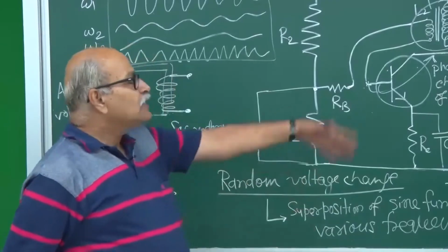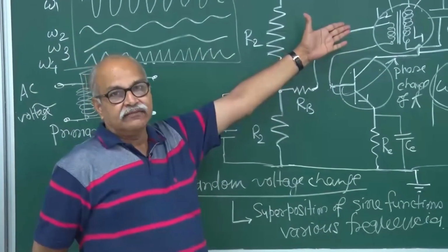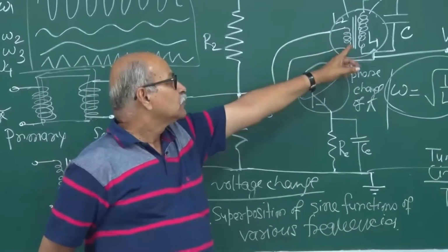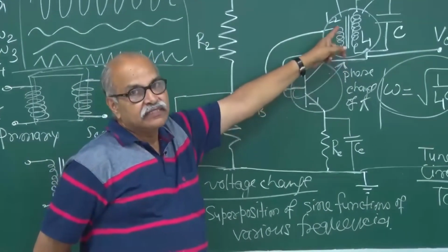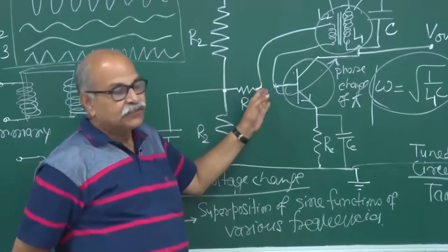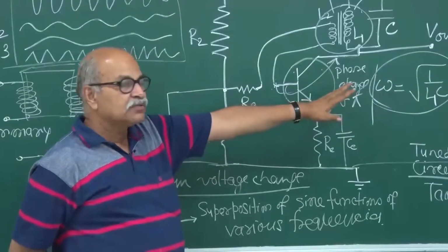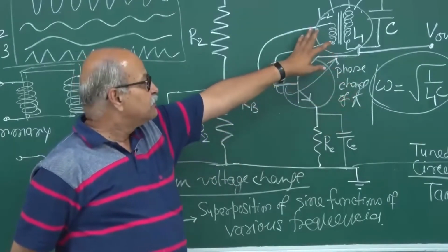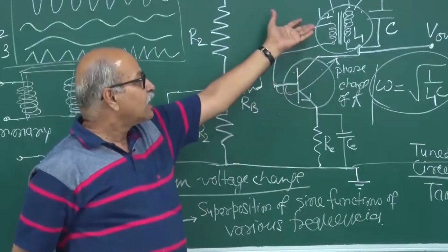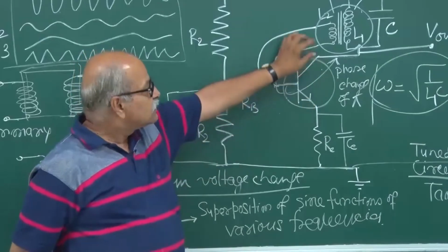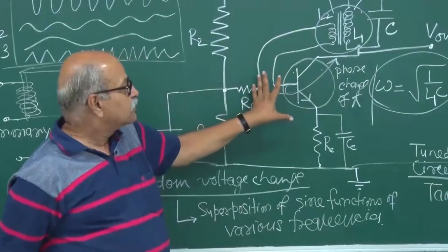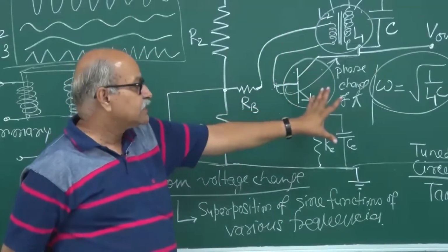And you get your output with that kind of voltage. How much feedback is taken can be adjusted from this L2. So the number of turns here will determine what fraction of this is taken as the feedback. Essentially we need a constant amplitude at the end of it. If this feedback is more than that, we are in trouble, and if it is less than that, we are also in trouble. So the number of turns has to be chosen judiciously so that a particular amplitude is maintained.